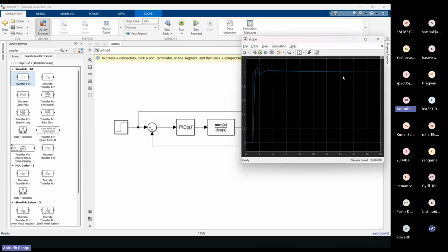So basically what we use proportional for is to reduce the oscillations and to get to the point of settling faster, because proportional is directly a multiple of the error. So you get these instant high changes of value, and you get to the point of settling faster, but it has its own issues.